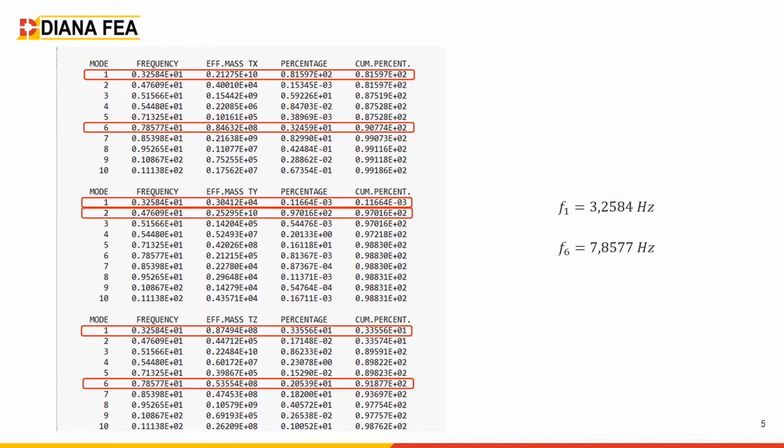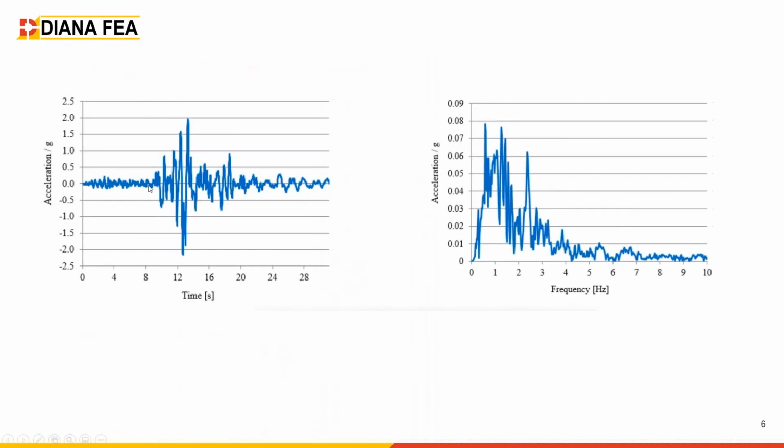So if we basically use this value, we can... I forgot to add something, which is also important to take into account at this level before we inject, let's say, this value. It's good to note that the choice of the frequencies, Fi and Fj, should also depend on the base acceleration used in the transient analysis.